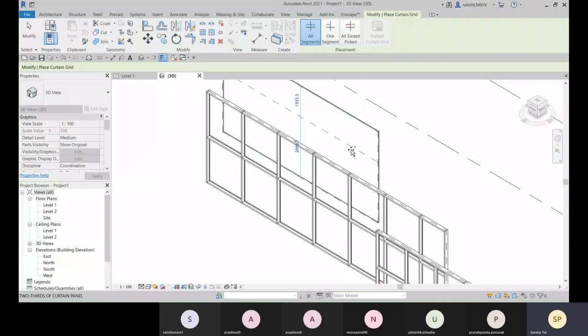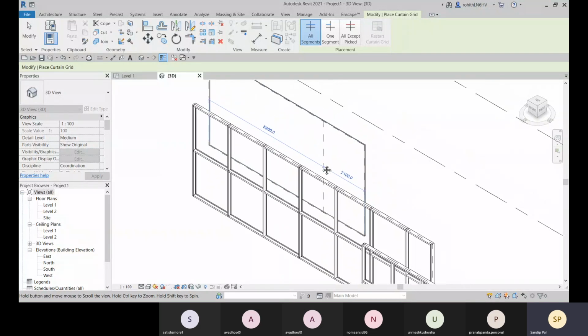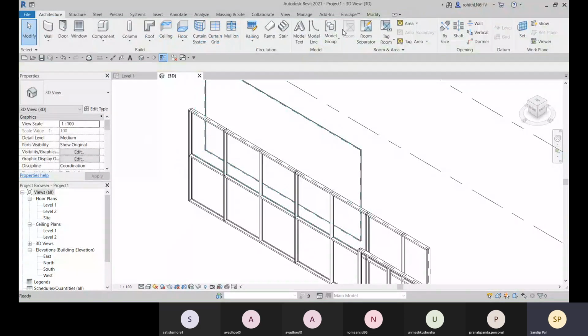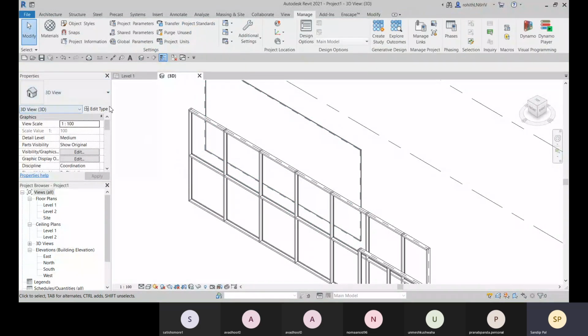And here you can see that Revit is showing you this dimensions, right? And you remember that the mouse pointer moving increment is right now 100. Accordingly you can place it. Okay, so let me show you where you change this increment snap.